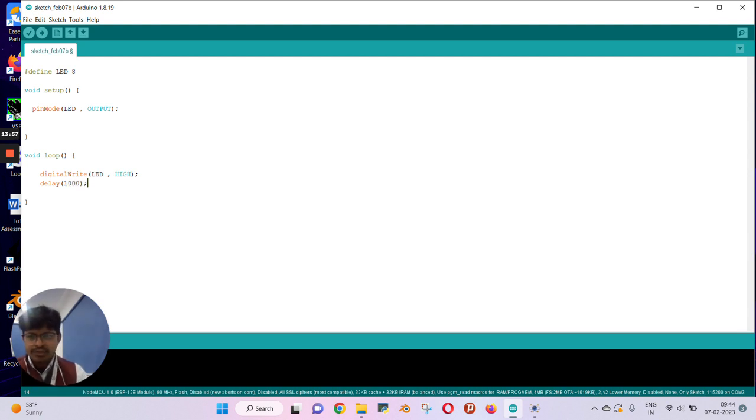In the delay we write 1000, because 1 second is 1000 milliseconds. In this body we write the value in milliseconds, so 1000 milliseconds equals 1 second. So our LED will be on for 1 second.